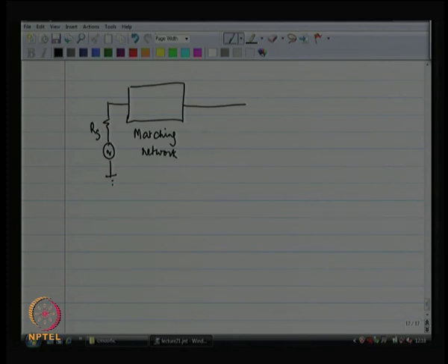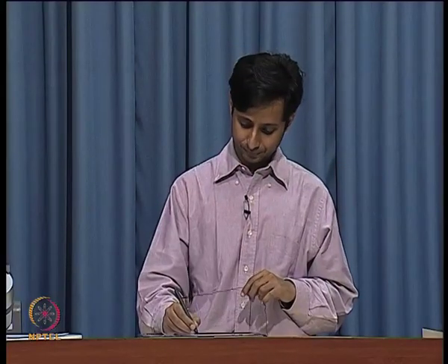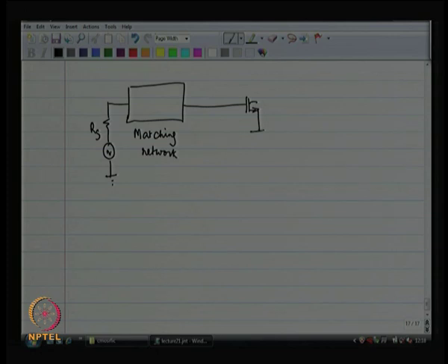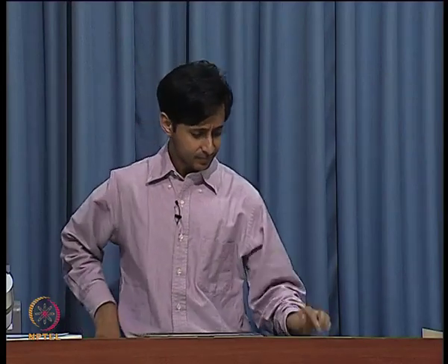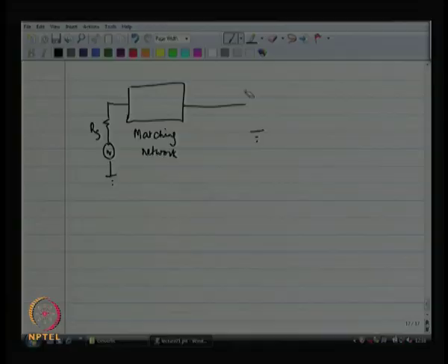and I need an amplifier, but the input impedance of the amplifier should have a resistive component. I like the gate of the MOSFET to be an amplifier, but the input impedance of that is not resistive at all, in fact it is capacitive. So, what do I do? One thought is that maybe we are making a mistake by putting the gate over there, maybe the gate is not necessary. We know other structures of amplifiers, we do not need to put the gate all the time.